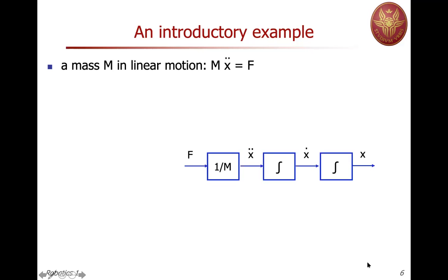You move one step, a differential step before, so you go in the reverse direction of the integration, so you have the derivative x dot, and you have another integrator, so you have at the input an acceleration, and this acceleration is nothing else than 1 over m times the applied force. Now, if you were able to apply force directly with your motor, then you can command the motion of this mass in the way you wish, following the trajectory, rest-to-rest motion, whatever, okay?